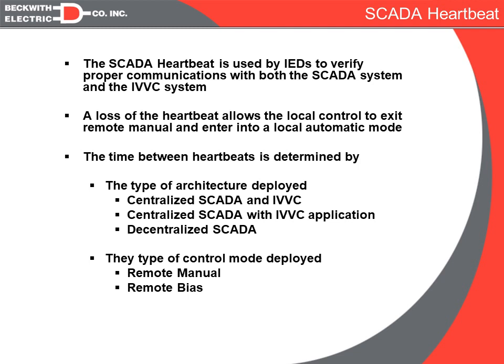So, in either mode, we do have to protect ourselves against a loss of communications. As a central program, we are anticipating that the central system is going to make the majority of the decisions, and if the decisions can't get out to us, then we have to know to fall back into a mode where we start making decisions on our own. And that's where the SCADA Heartbeat comes in.